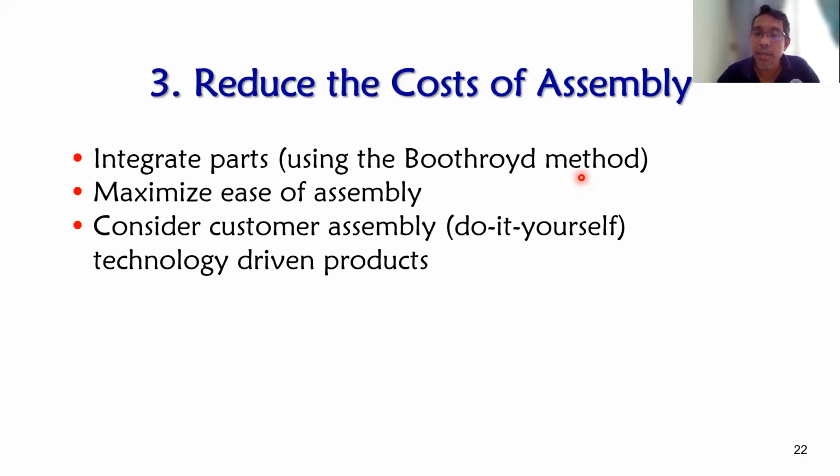So if you think about assembly, for the critical geometric features you also need to assemble well. Some are very difficult to assemble with precise control on that part. But when you use molding to make that part, the critical geometric features are already controlled in one single manufacturing process.